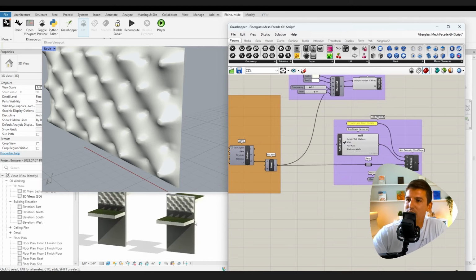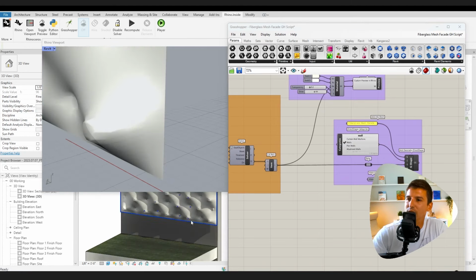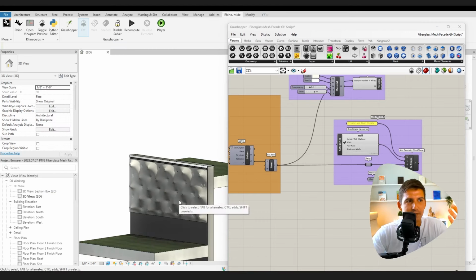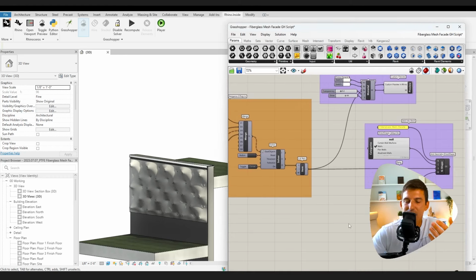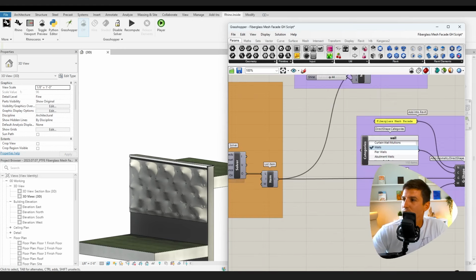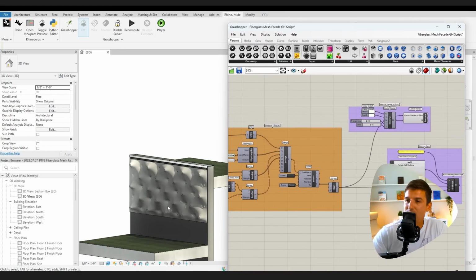And so we should be able to then see that update in Revit. And at that point in time, you probably don't even need the Rhino previewer. And here you see that we used Rhino.Inside really just to run Grasshopper and Kangaroo. And we didn't really need anything further in Rhino in this case. However, you could be drawing items and curvature in Rhino. If you need to reference that in your Grasshopper script, you're welcome to include more geometry in Rhino and ultimately send that back into Revit, even though it never initially existed in Revit. So that is the script in a nutshell.